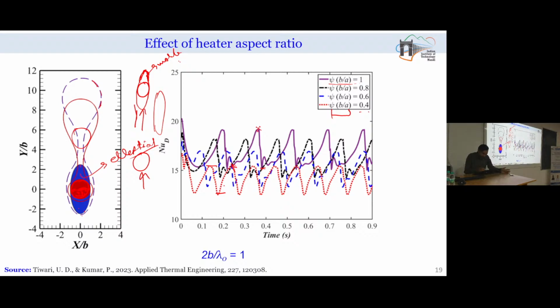However, if you see the overall period of bubble formation and its rise, it is almost 1.5 times that of the period for the cylinder shape. Okay. So, though we will get a lesser heat transfer coefficient, the number of bubbles forming at this surface will be more in comparison to the number of bubbles formed on a cylindrical surface.